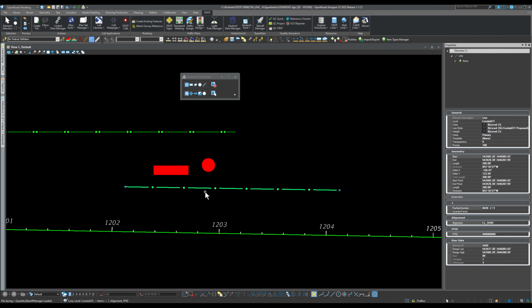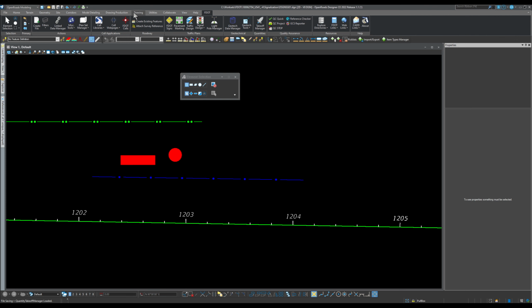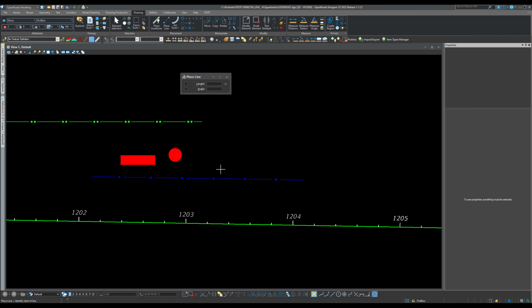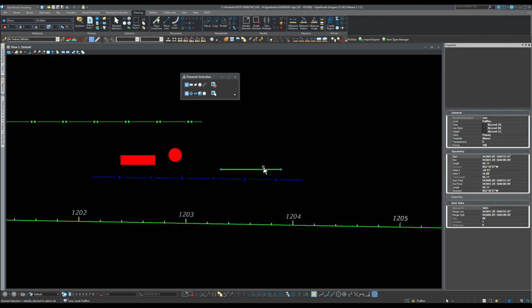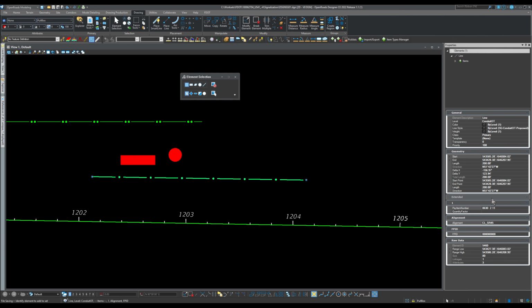So what if somebody, for example, just imagine with me, you are drawing this, it's 200 feet, but you want extra slack. You want extra added to your line, but you don't want to draw it, because some people, what they do, I noticed, is draw a line and put it non-plotting. Well, you shouldn't do that. There is another way, which is why I added these quantity factors. So this is a 200. If I just leave 1, it will literally multiply 200 by 1.